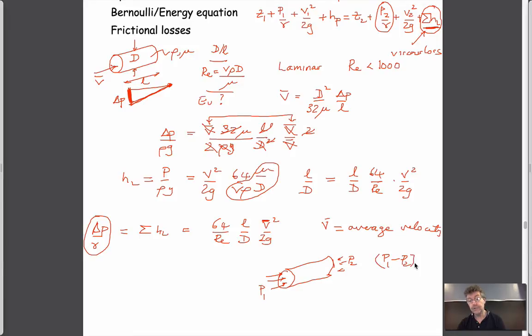and the force due to those is the difference between those multiplied by the area, right? So if you're balancing momentum, there is no change in velocity in this system because it's a constant section area pipe. So the velocity at this upstream end has to be the same velocity here, so there's no change in momentum.